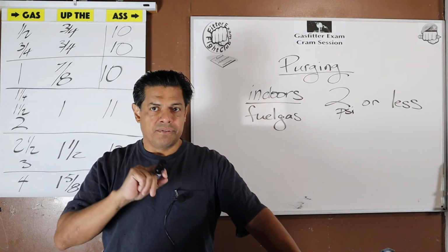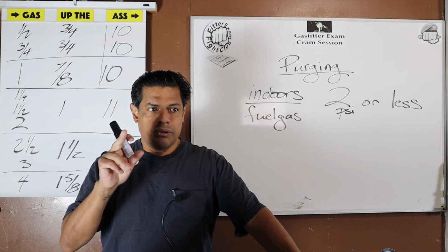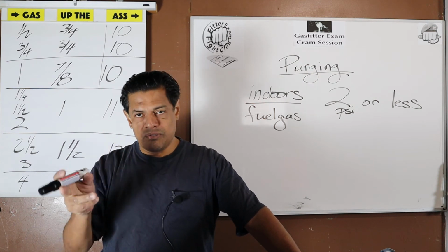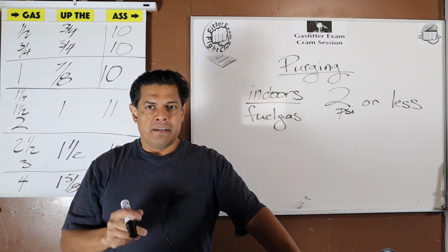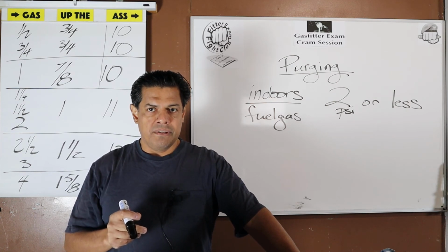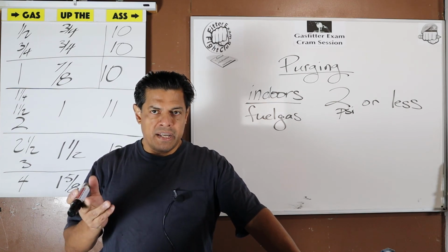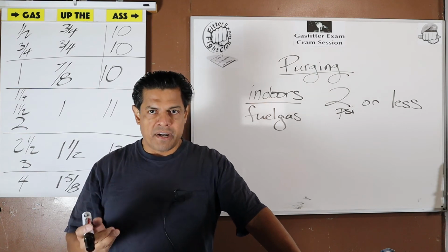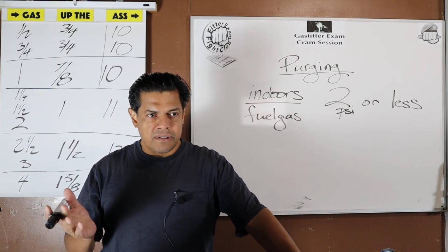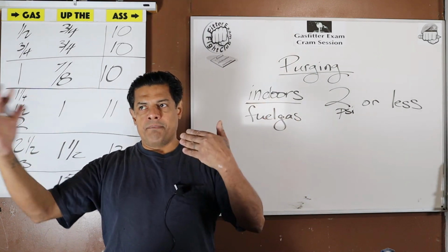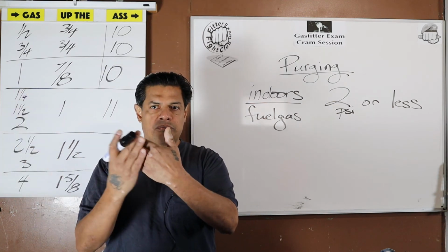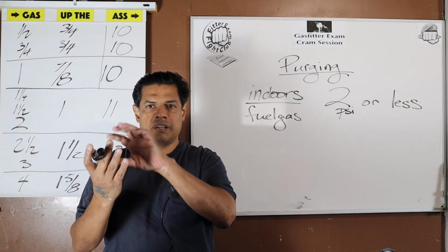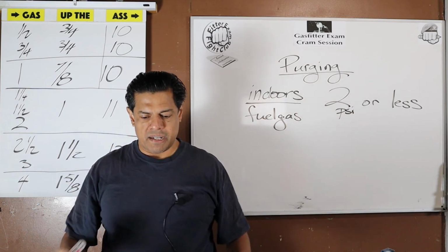After the lockable supply valve, we were allowed the test T, the drip leg. Didn't mention anything about a union. What would we use in that case? A left-right coupling. If we have piping coming from two directions, the threads, you're never going to be able to make that up. The left-right coupling, you can make that up.